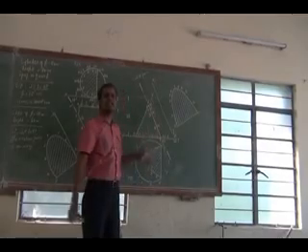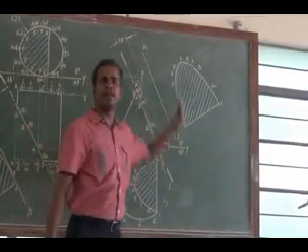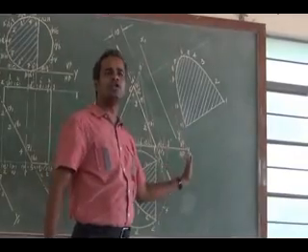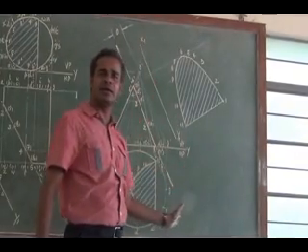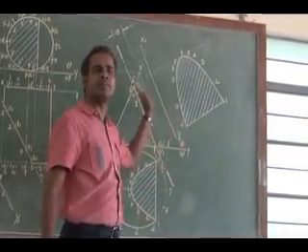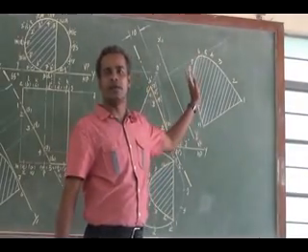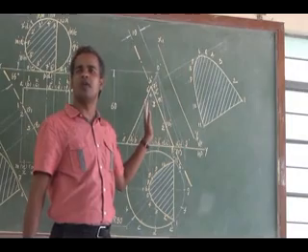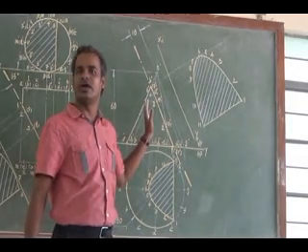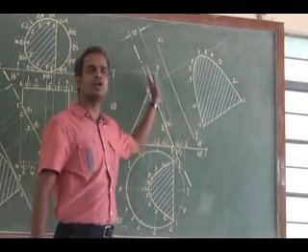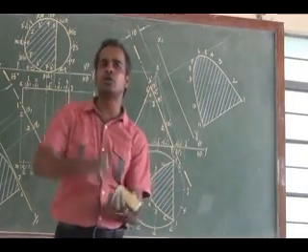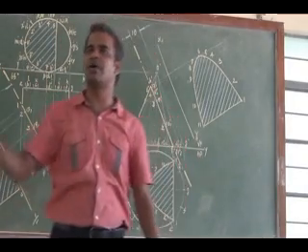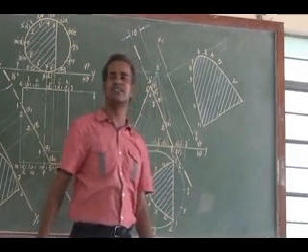Once you have got the sectional top view, in the same manner you draw to get the true shape, you draw a parallel line. That is a new reference line parallel to your cutting plane. See here, this is a cone. What is a conic section? What we have seen in the first unit itself. The cone is cut parallel to a generator. What will be the true shape of the cut surface?